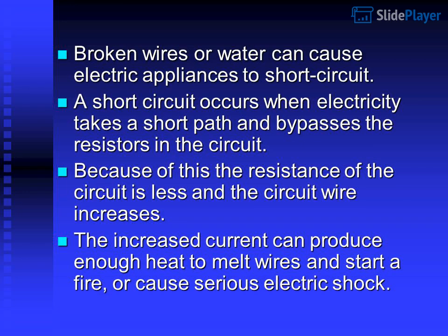Broken wires or water can cause electric appliances to short circuit. A short circuit occurs when electricity takes a short path and bypasses the resistors in the circuit. Because of this, the resistance of the circuit is less and the current in the wire increases. The increased current can produce enough heat to melt wires and start a fire, or cause serious electric shock.